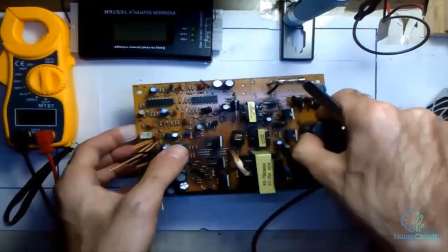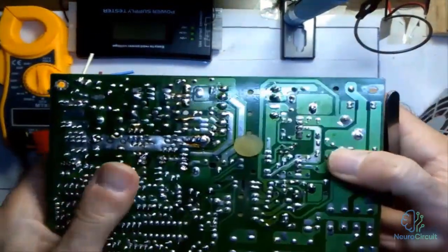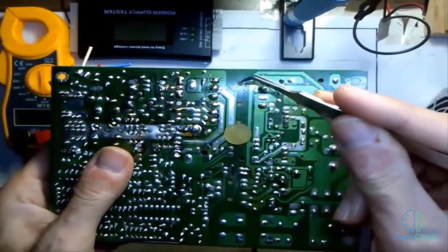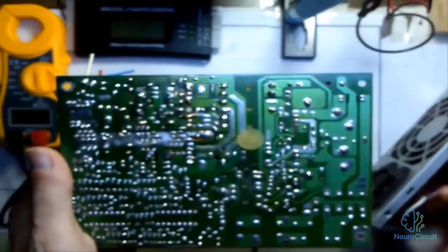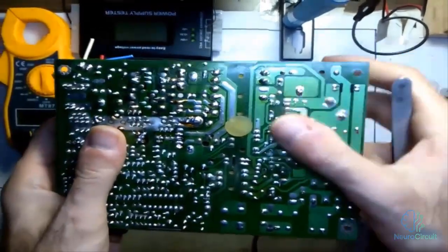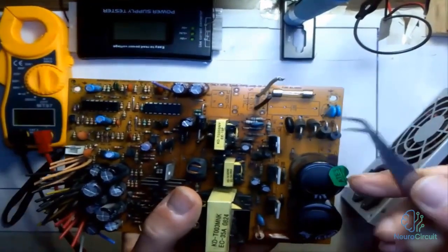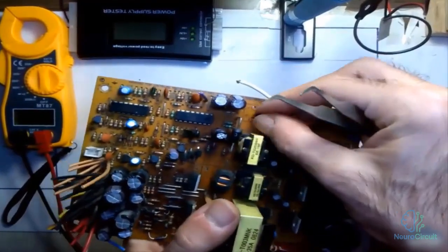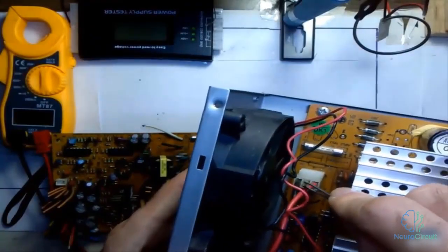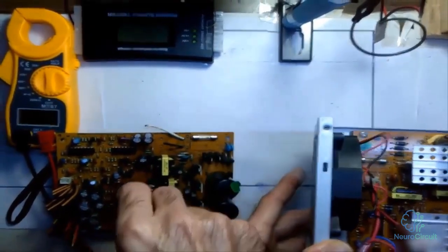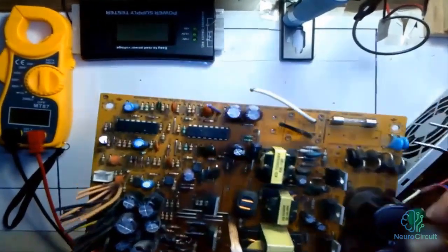So we'll start working on the power supply like this, by disassembling it. If I show you the back of the power supply first, here you can see the separation between the primary and secondary circuits. This part is the secondary circuit, meaning this side, and this part is the primary circuit. When you connect power to the power supply, through these wires, which you can also see in this power supply, are in the form of a socket. But since I opened up this power supply, it's easier to see. I'll explain again using this open power supply.